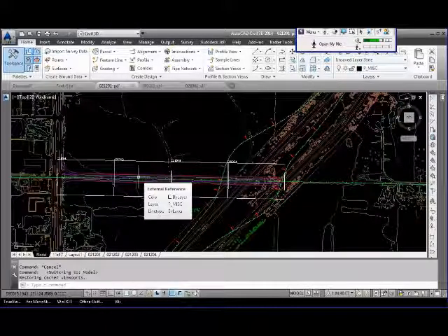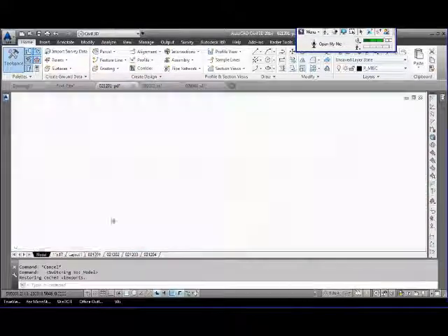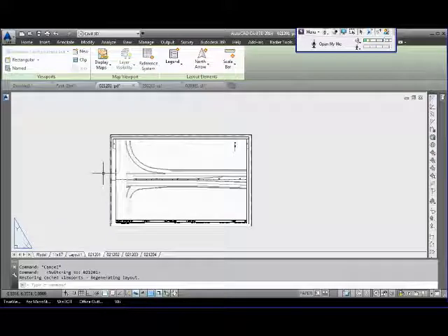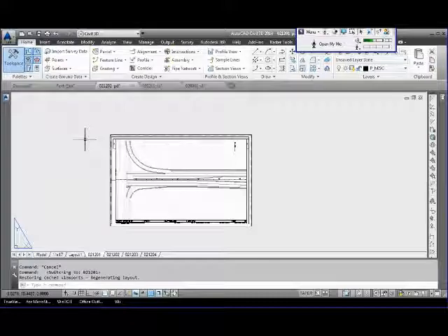And I'm working in a vacuum here, really. I have all my files on my C drive. I'm not on the network. It's not really realistic, and we can still notice the difference between switching over. So a lot of people have that layer manager open. I just pop back to that tab real fast. So think about what you have open, layer manager, other stuff. If you're working on sheets with a lot of references, a lot of layers, it can really save you time by closing the layer manager, jumping back over, and then reopening it, if you have to. Sometimes you don't even need to.